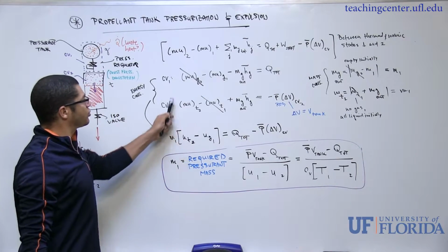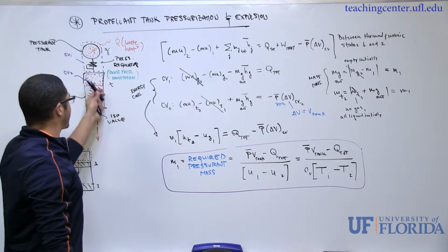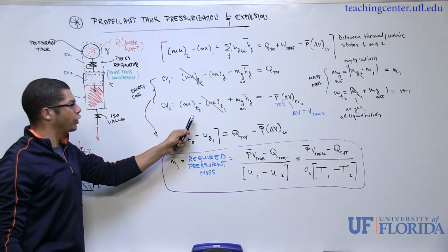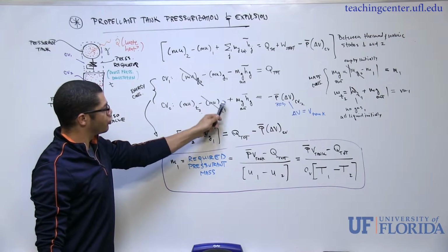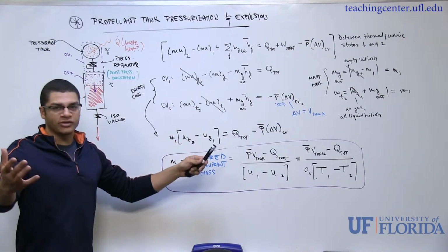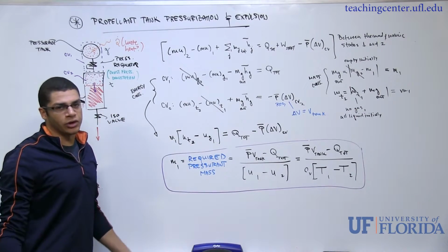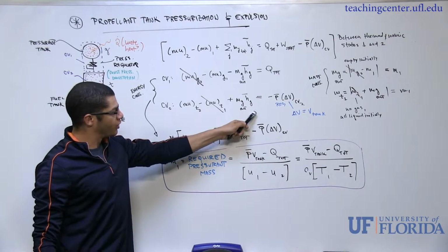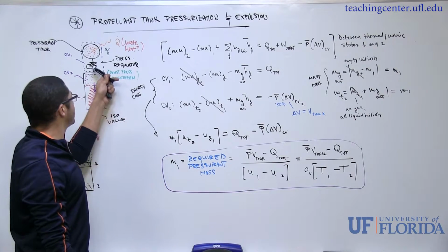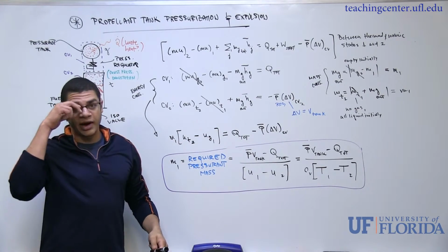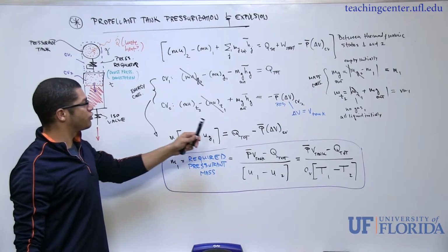So the final condition here, the final internal energy of the gas, when the control volume coincides with the entire tank volume, and this would be minus the internal energy of the gas initially. We can say that there's nothing in there initially, so we can cross it out. Plus, during the course of the time that we're concerned with, there is going to be an inflow of gas from the pipe that's connected to the tank, which is downstream of the regulator.